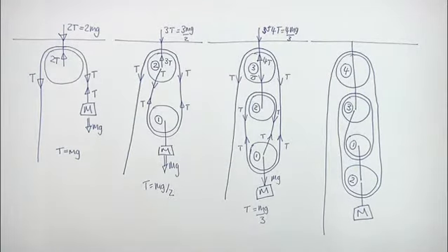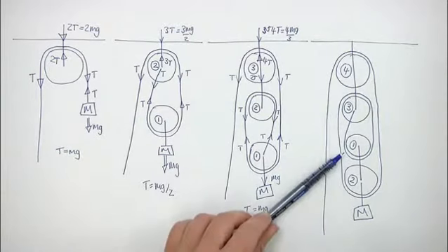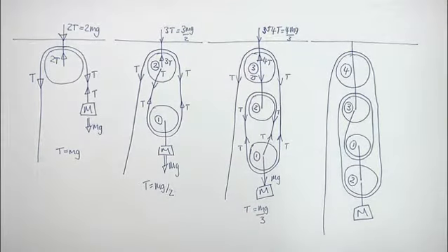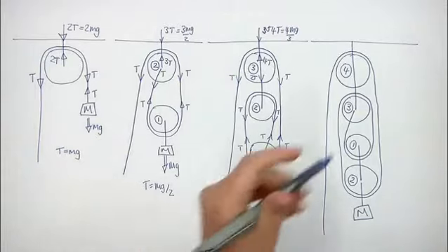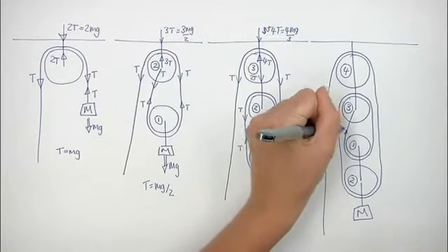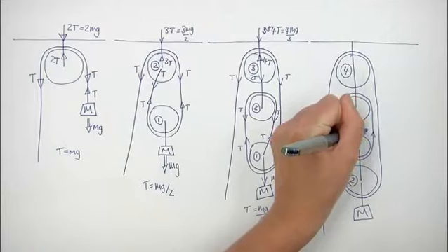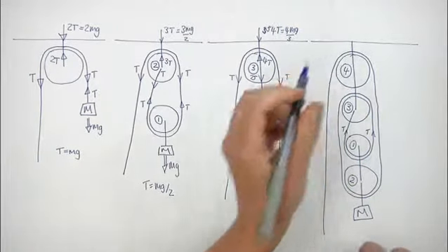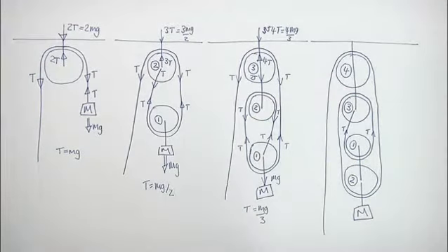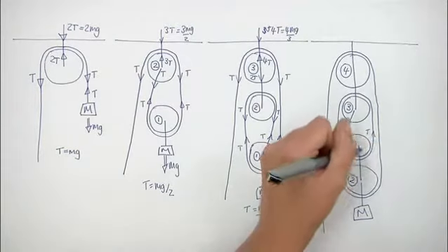Finally, a system of 4 pulleys. It gets more complicated to draw and harder to see. Consider pulley 1. It's got a rope pulling it up with tension twice. It's also supporting the lowest pulley. So the force that the lowest pulley is putting on it must be 2T.